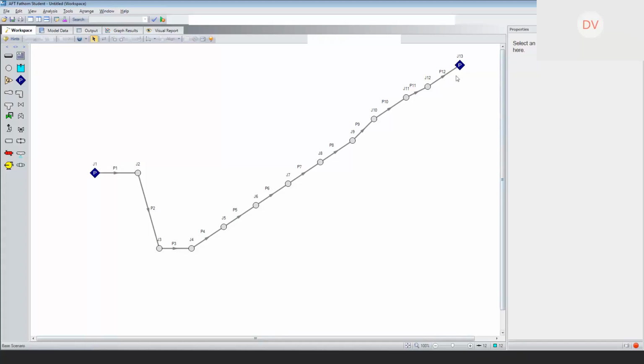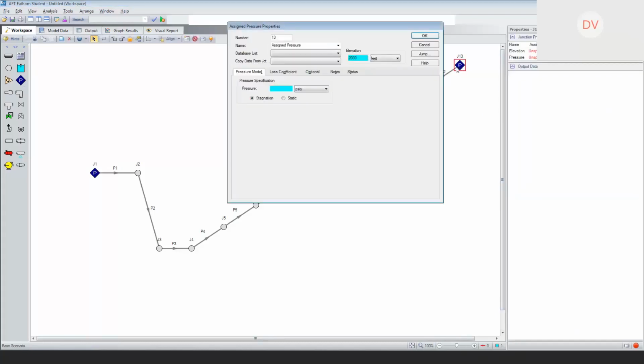And I'm actually going to run it after I put this in, because we're here already. The elevation at this location is 4,000, so you know that the starting point's 2,000 feet. It drops in elevation down to 0 down here, and then has to do a rise of 4,000. So there's obviously some elevation head pressure that's going to be working against you. The designated delivery pressure is 50 psig, so I'll make that adjustment as well. So it's just those two input data there.